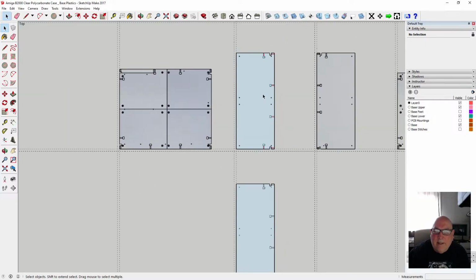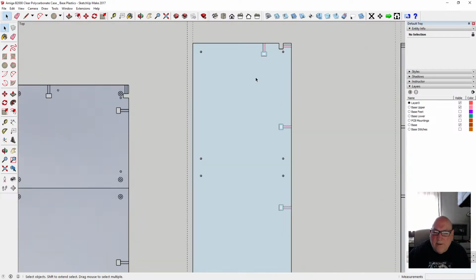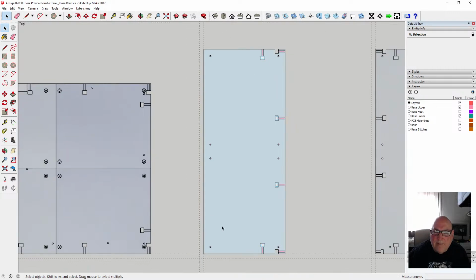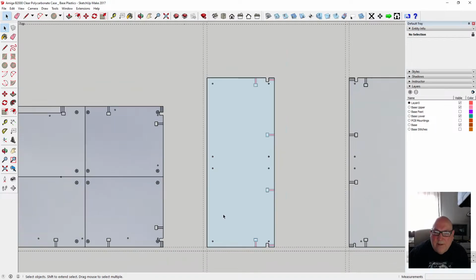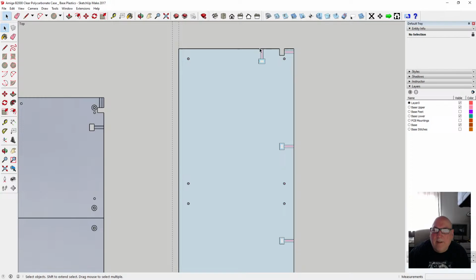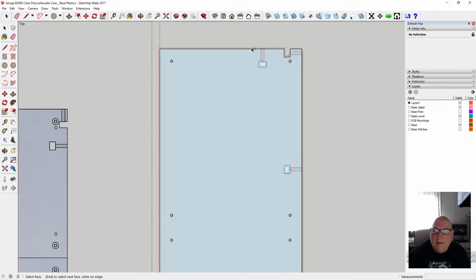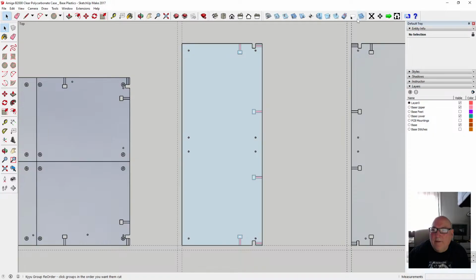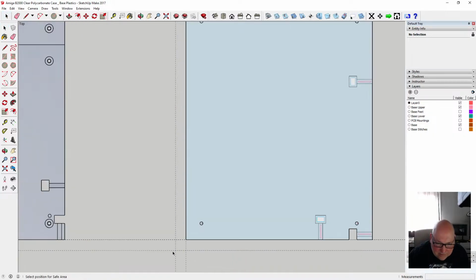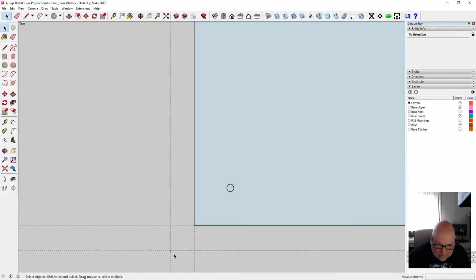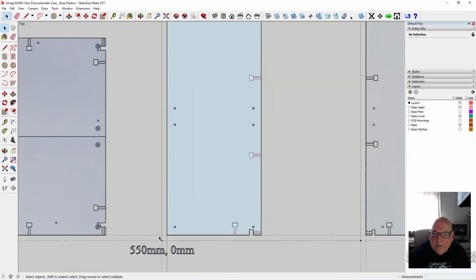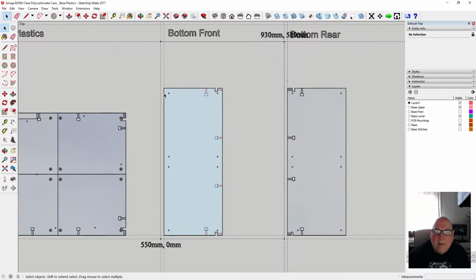So we've got our pockets, our inside cuts, and our plunges. Now we can't do the last one, which is an outside cut, because it wants to do an inside cut, so that won't work. So we'll leave that bit, and we'll put the safe area around it now. Over here, that automatically lines itself nicely. Right, so which means we can just click save. We can generate some G code.